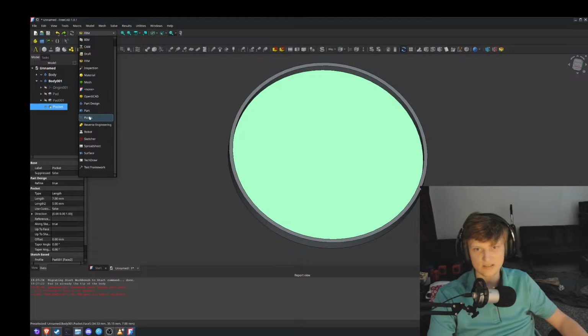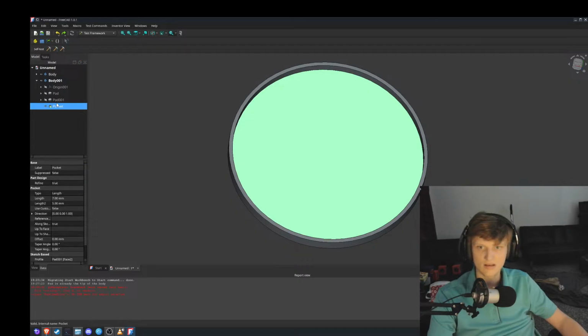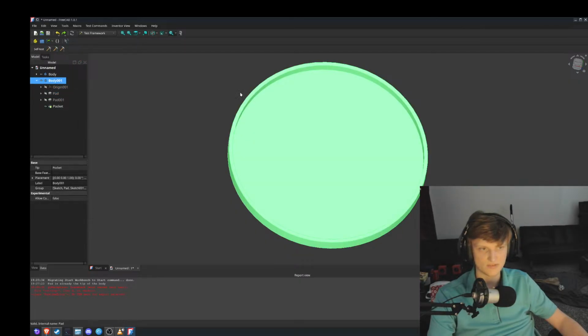Is that one of these things? I'm guessing it means just select it in this view. All right, I selected the body in the tree view. I'm guessing this is what the tree view is, this left thing. Then switch to the mesh workbench from the drop down. While you have your body selected, click on the menu option meshes and choose create mesh from shape.